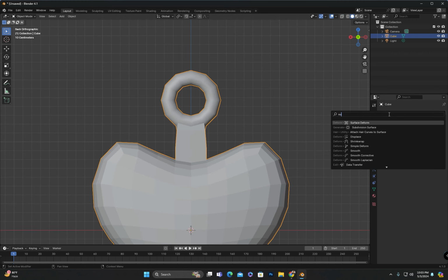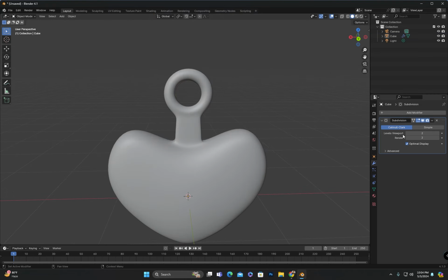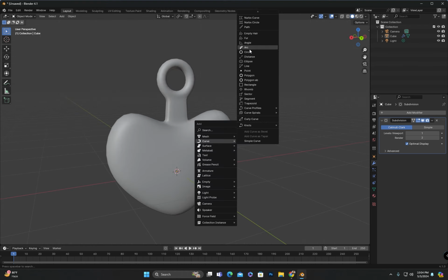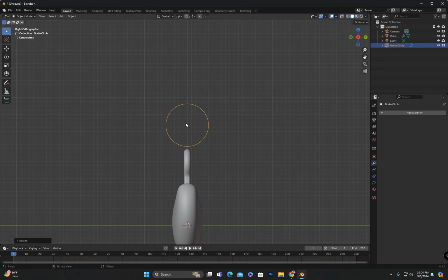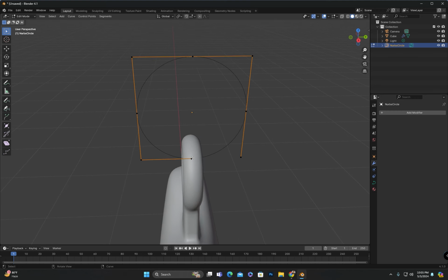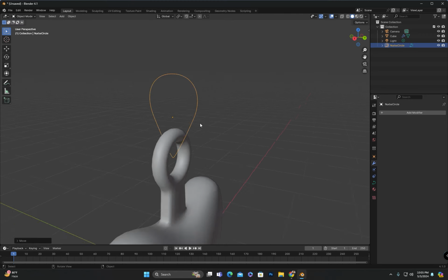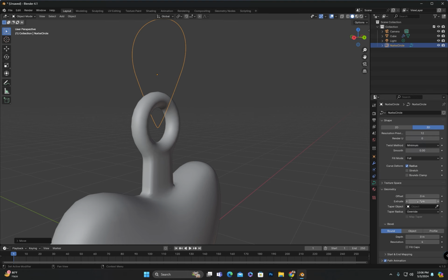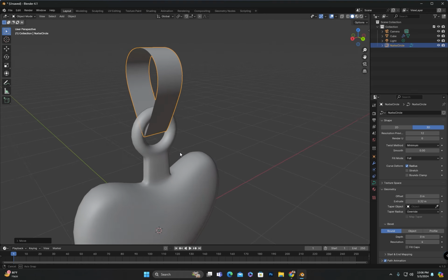And now when I apply the subdivision surface command to it, you will see that we have a much better design. I will create another circle curve here because I need another shape. After adjusting the shape, I will input a value to extrusion in the curve properties and reduce the resolution value.